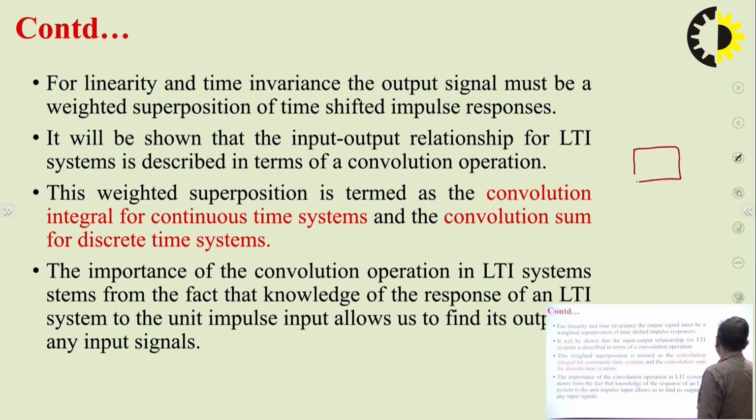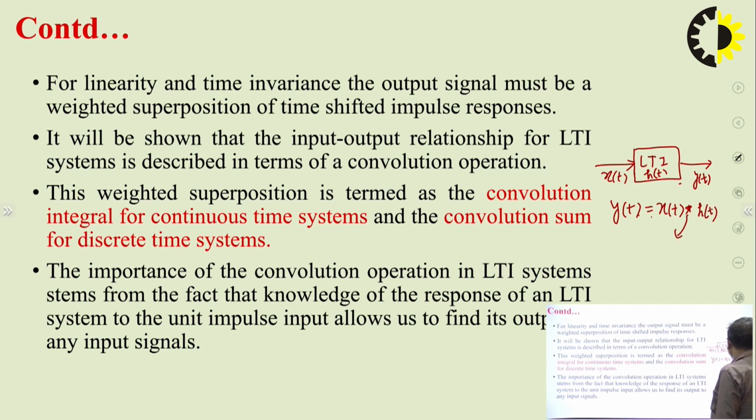Suppose we have an LTI system with impulse response h(t). If we apply input x(t) to this system and get the output y(t), then the output can be calculated as y(t) equals x(t) convolved with h(t). This operator is called the convolution operator, and this process is called convolution.